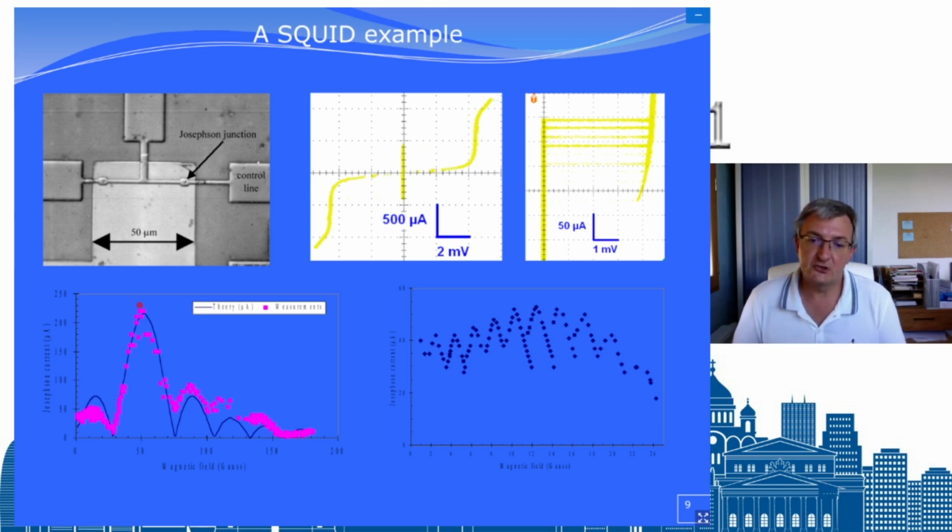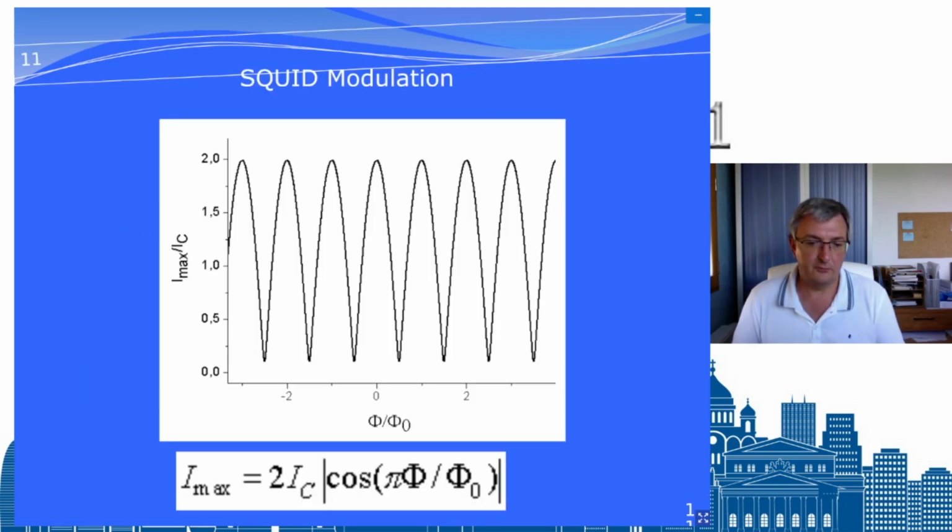But anyway, you want to be in this area, only at the maximum, so you avoid flux trapping. And in fact, with a good SQUID, you will have a small loop here, so you cannot have many fluxons. You can have only one. So you will not see all these details. You stay here, and then you will have the good properties to have the best modulation. Otherwise, yes, the modulation decreases.